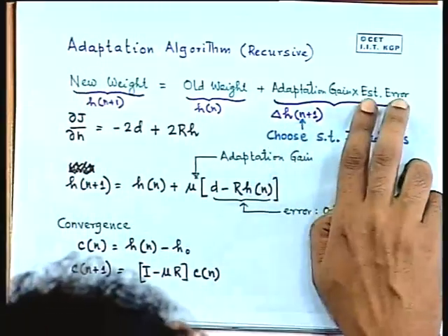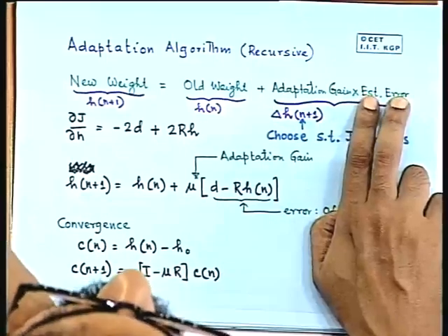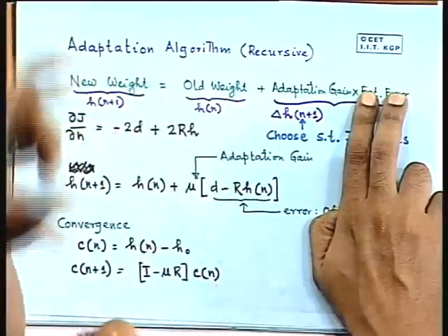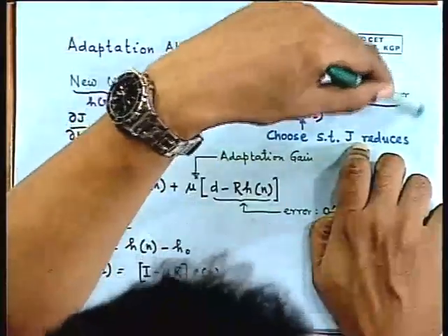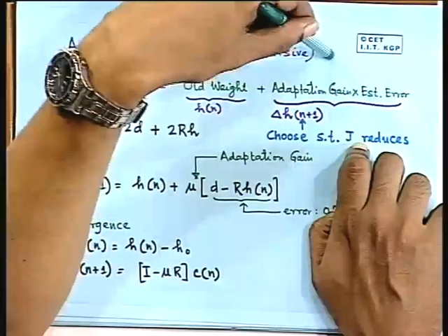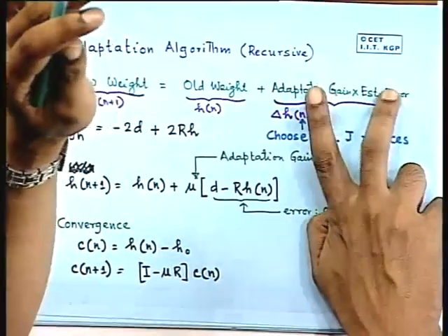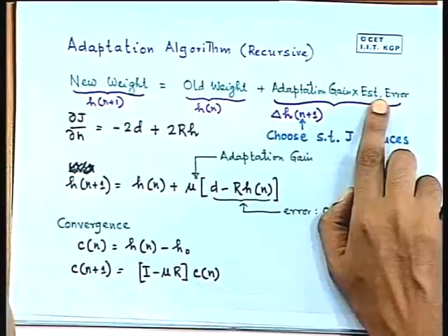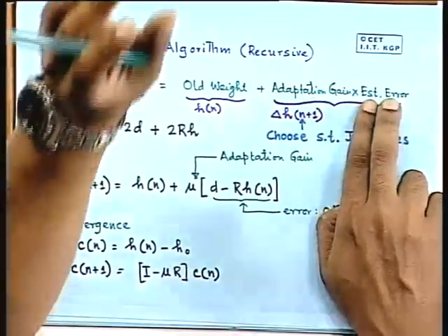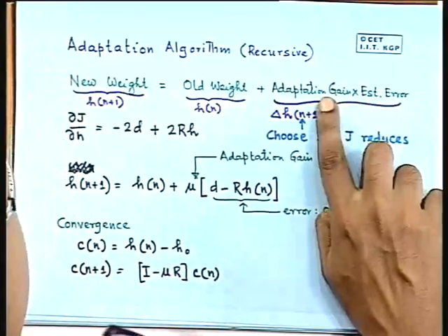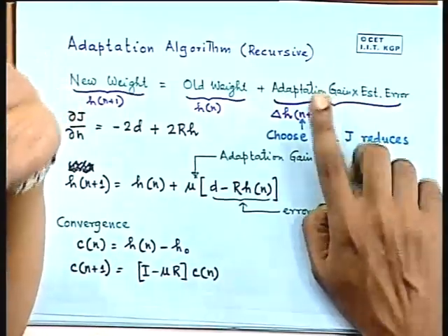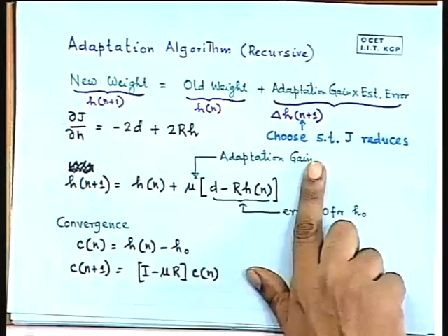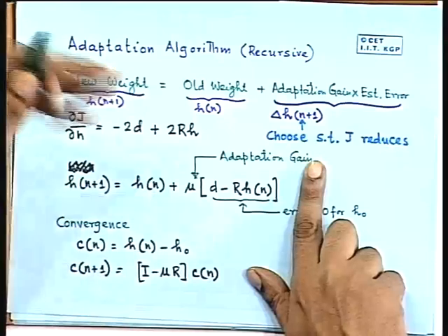So you will always compute whether the weights are really good in terms of some kind of an error. All algorithms vary in defining this error, defining this gain. So all variations come because of these two definitions. Otherwise, they are generally in this form. So you will define some error, and then based on that error, you are going to change it using some gain. So these two remain to be determined. But this is the structure in which you always adapt your system.